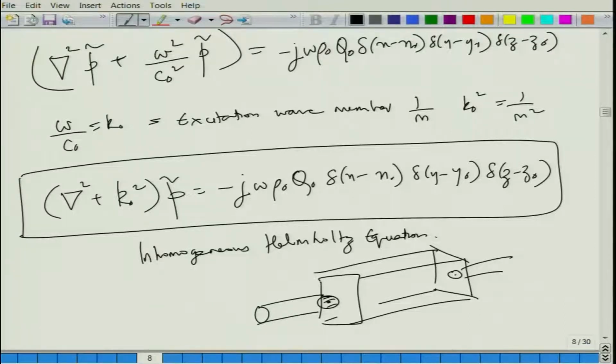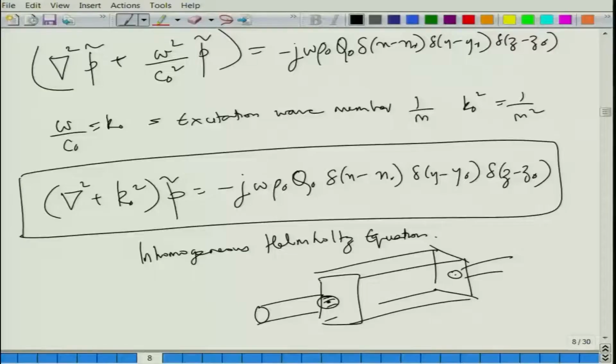Now, there are different theories that are used to characterize mufflers. The simplest one is the point source representation, which assumes finite size ports to be points, like I said. Then you have methods like a uniform piston model. Basically the finite port is still represented by a finite thing, but over this entire cross section area the velocity or the pressure fronts are assumed to be uniform.